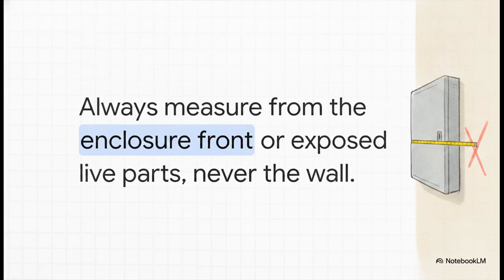The exam writers will totally try to trick you by saying you measure from the back wall, or maybe from the center of the bus bar. Never fall for it. You always measure from the front of the enclosure.